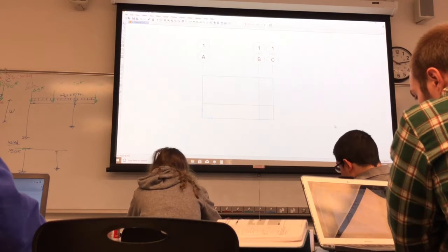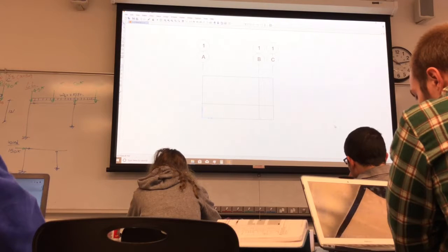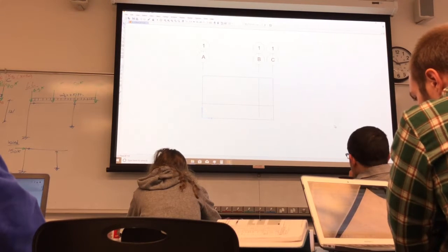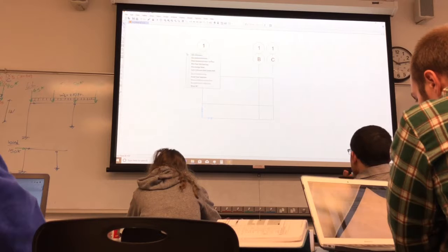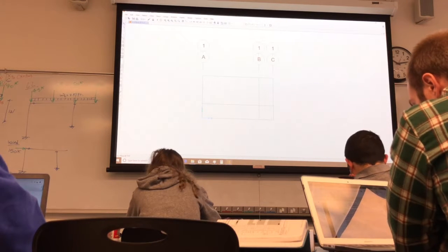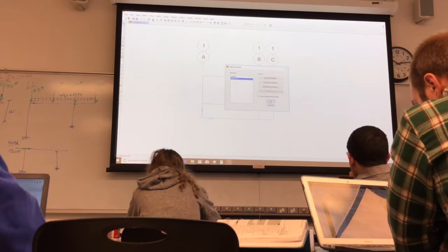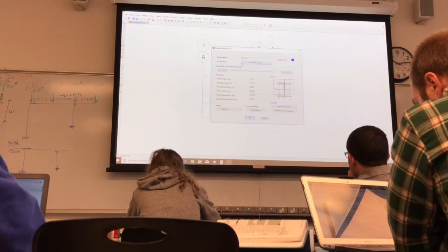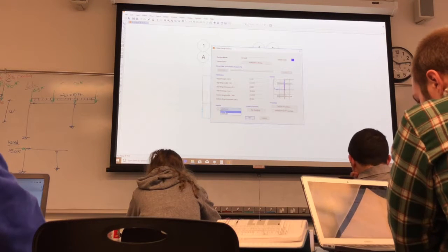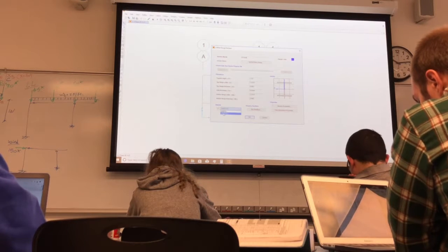It's not a problem. So again, what I did pretty much is that I defined the grid lines. That's the first thing I did, by new properties, put grid line, new model, and then I edit grid lines, and then I defined materials, made sure I got the right material A992, and then I got the sections. You want to make sure that the sections, there is an option here in the section, show you the material used. So SAP already assigned A992, which is good. You don't want to assign 4,000 PSI, that's concrete, right? So you keep it steel.